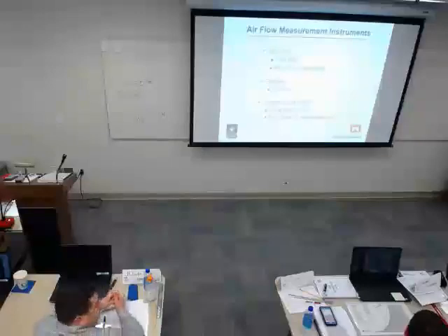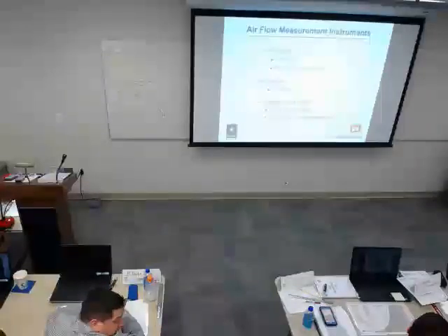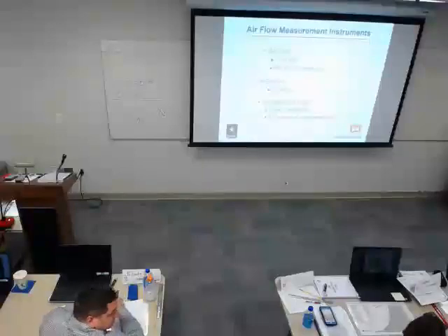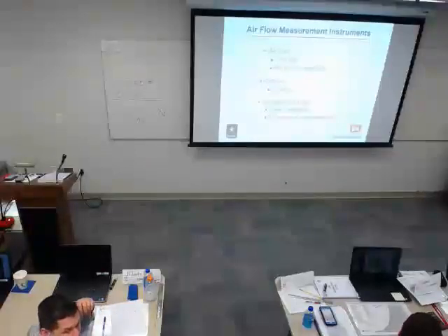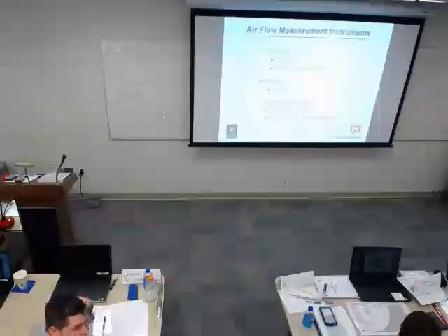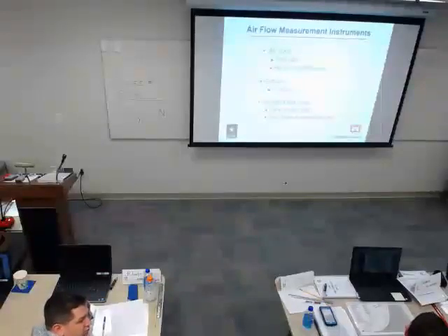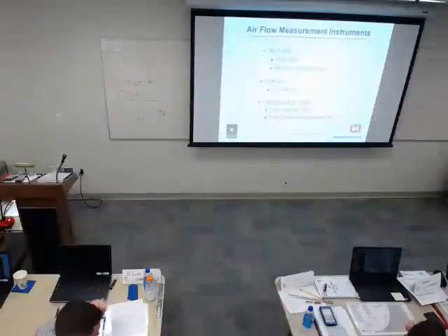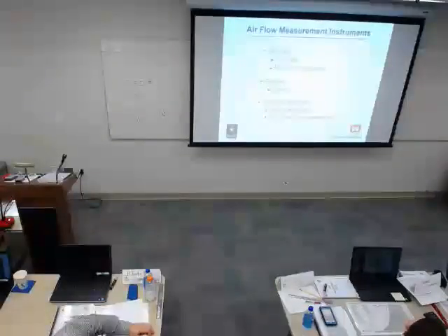On those right there, that's another place where it's really important that the air hits the diffuser square, because you can get air drawn through the side that's not flowing out, and so your airflow measurement may be higher than what's really there. So just know that it's real important that you have uniform air all coming out. If you want the center, you might see a difference in the reading.